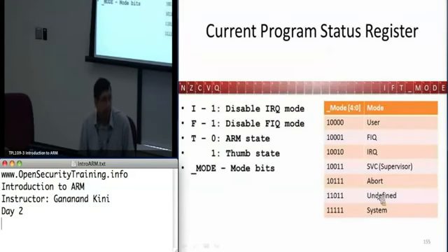So if you remember, I'd shown you guys the CPSR actually has the mode as the first 5 bits. And each of the modes have the following encodings, which are up on the table. The ones we've seen so far are supervisor mode. When a SWI occurs, the mode changes to binary 10011. And when it switches back to user mode, it has 10000.